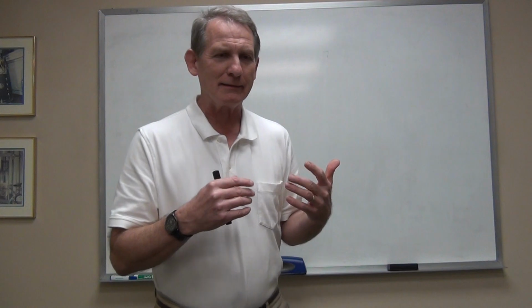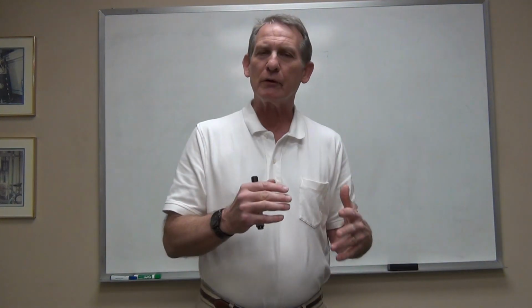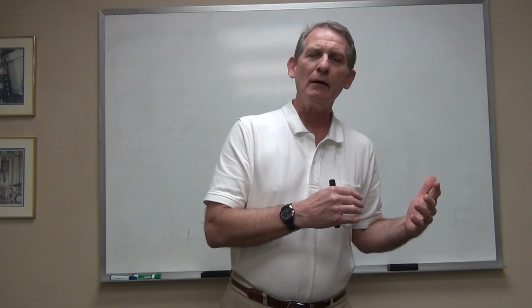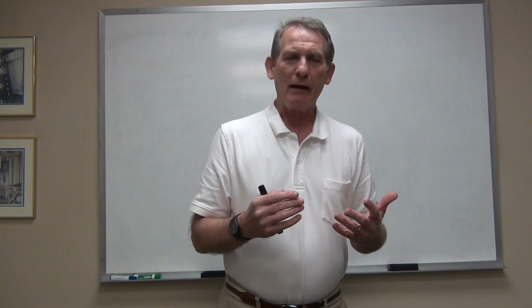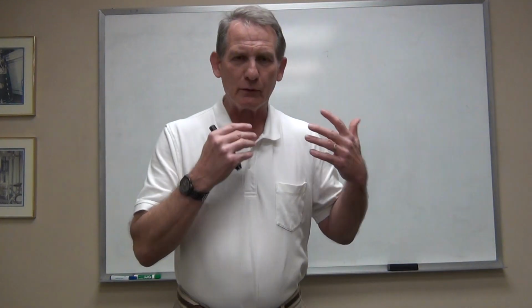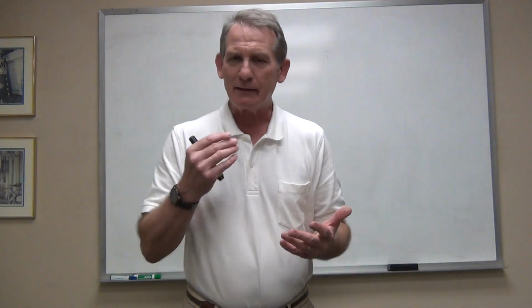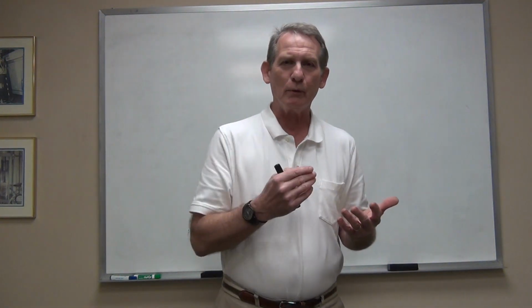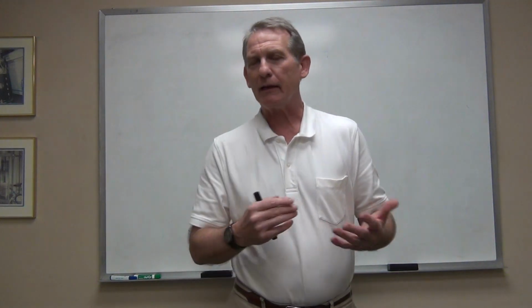And what it means is that if you have a material condition modifier and you have good control of the size of a feature, in other words, if you're turning a shaft and let's say you have 10 thousandths tolerance on the diameter of that shaft, and you can consistently put it within a couple thousandths, anywhere within that range, you can take advantage of that.